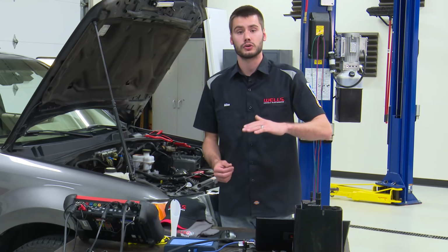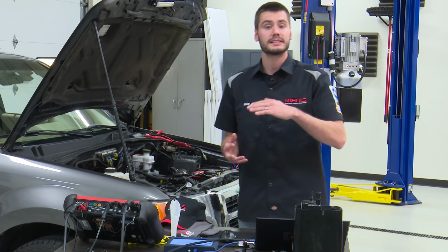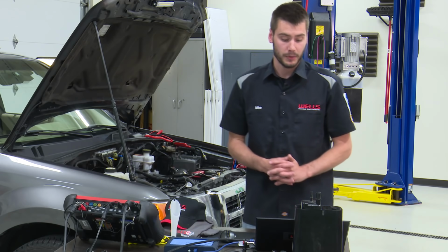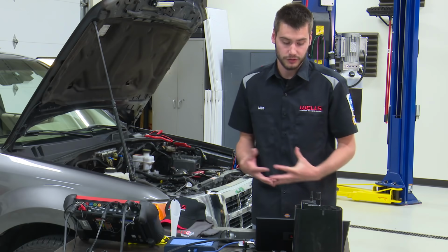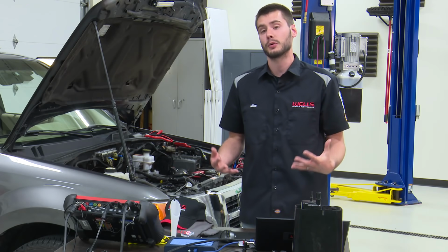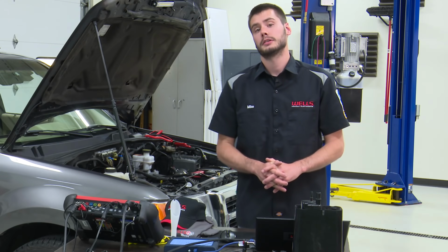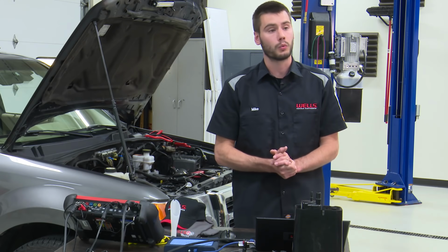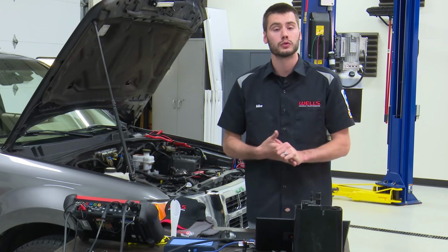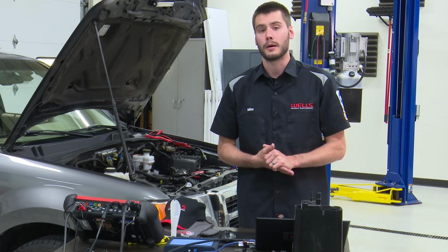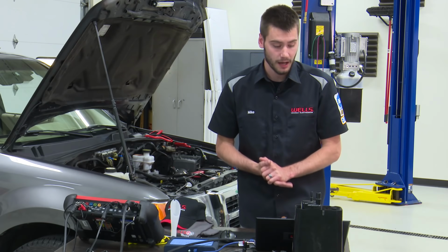Again, there is a threshold, a set amount of decay that is allowable in a set amount of time. And those are stipulated by the manufacturer to determine if it's a 20,000th leak, a 40,000th leak, or a gross leak. Now I have heard, and I don't know when or what models are going to have it, but I have heard rumor that we're going to start to see a 10,000th leak parameter or potential test on newer vehicles.